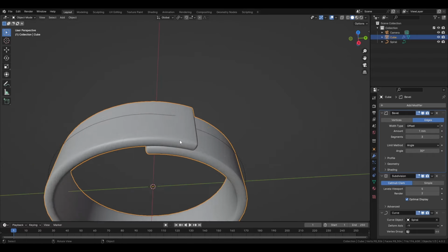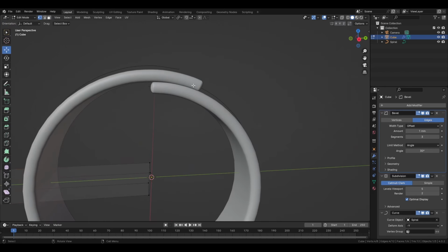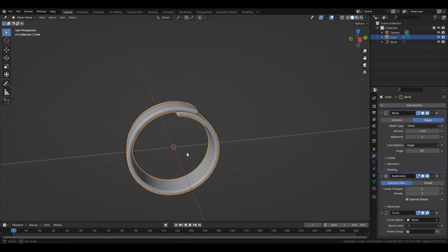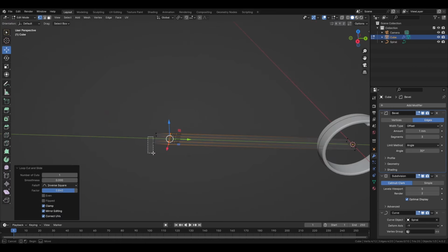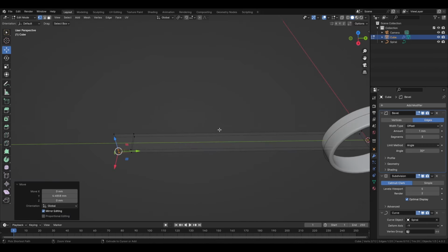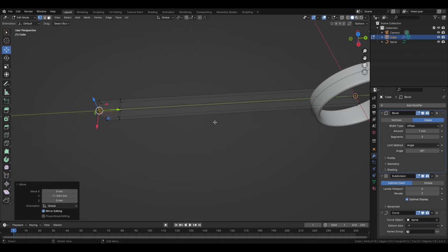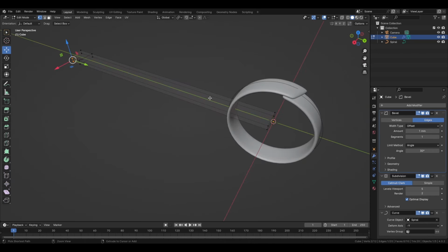And we can also modify the actual mesh. Actually, you see it's flat here because it goes further, so we might want to just change this here. Yeah, like this. You can add an edge loop here and change this. So if you want to change the geometry and have something a bit more interesting, you can also add one here. Move this. So you see it's going to automatically move this here. So yeah, you can basically modify your shape like this.